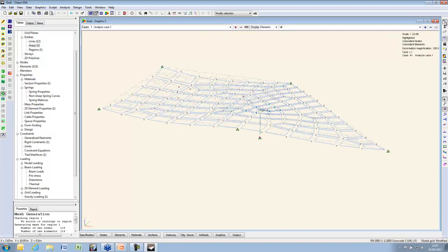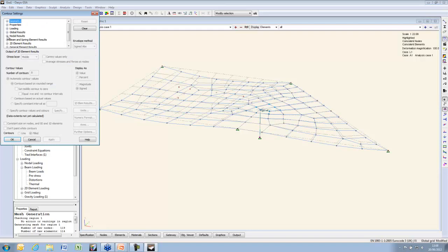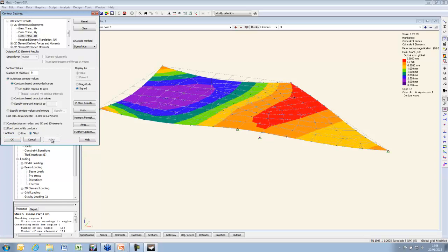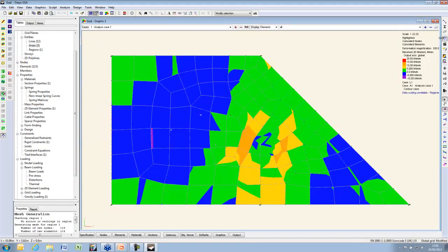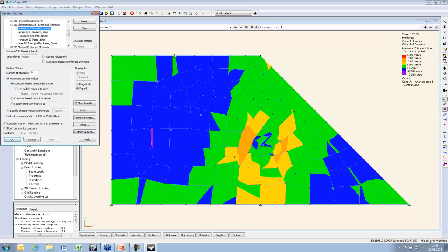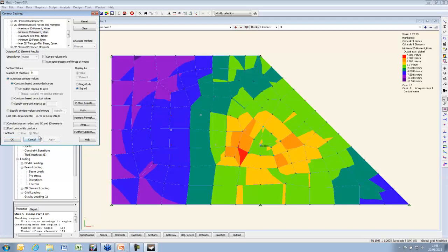We've got some deflections, which probably aren't very much. And from the results you then get things like overall forces. Let's look on the plan view in a minute. Note that these are linear or quad 4 elements, so the contouring is not very smooth. If we use quad 8, you get a much smoother result.